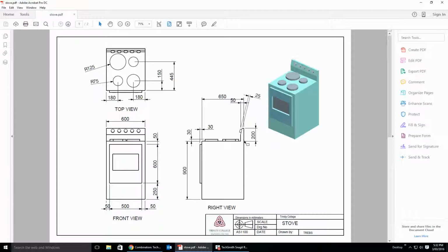Then we're going to extrude onto this surface here another feature, which we're going to draw on just as a line, which is going to have a height of 200. We're going to have a width of 50, and we're going to have a small dial that's going to be drawn on later on, small width out, and we're going to have an angle.